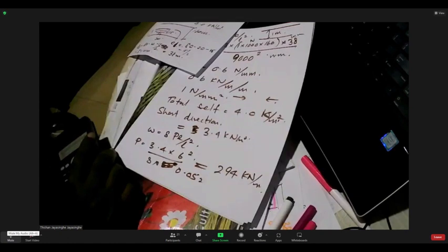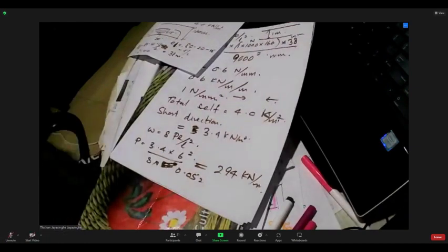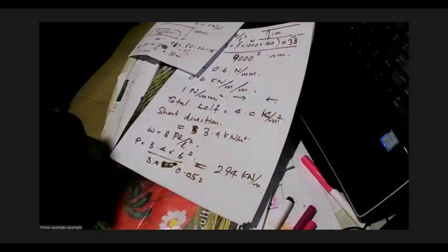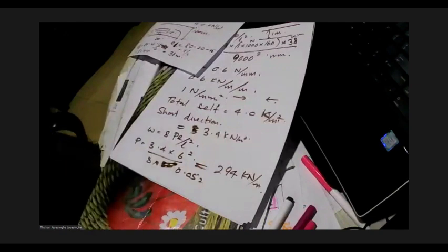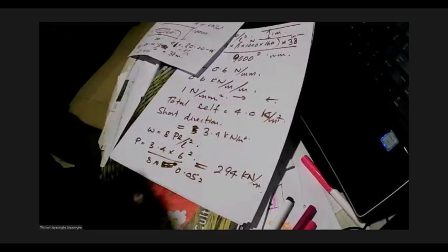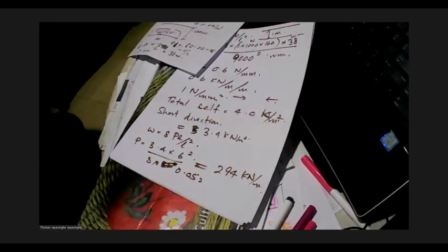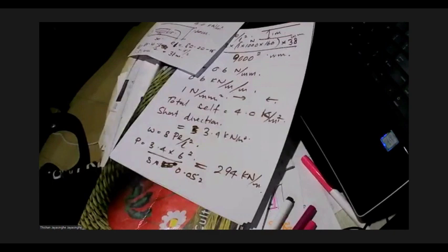Can you understand this? So basically what we are doing is we are balancing the load. We are trying to find a pre-stress that will carry most of the bending moment of the two-way spanning slab in the short span direction, and still it will carry some load in the long span direction. And the idea is to make sure the full weight of the slab is compensated. That is the concept. Is it clear, Vashika?